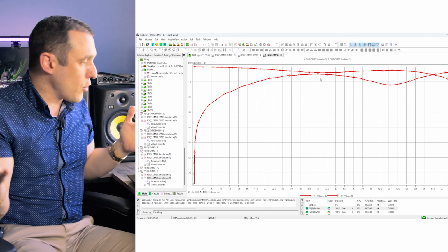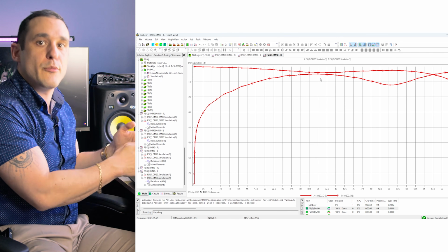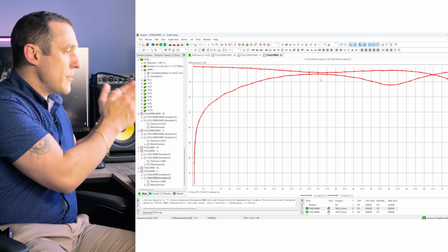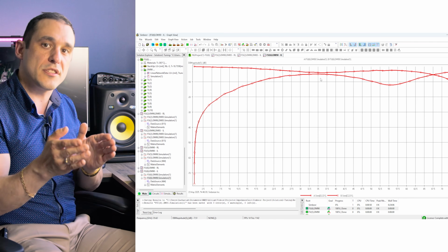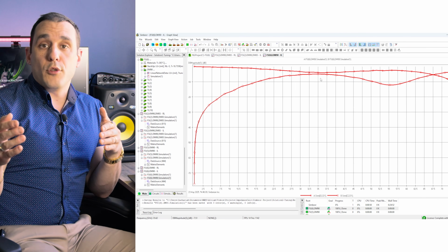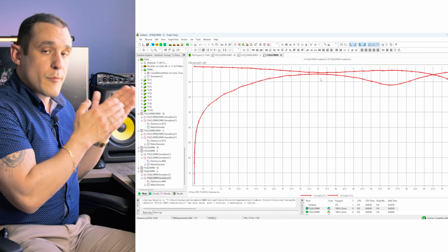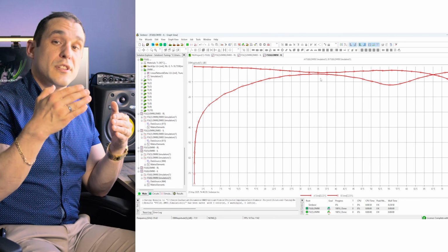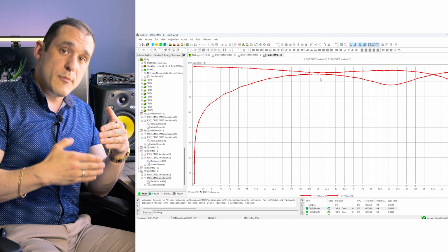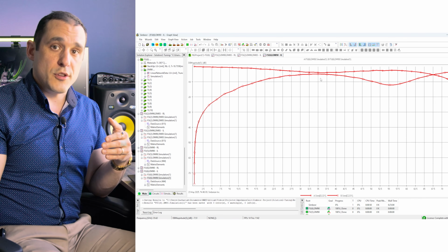The other reason this is important is because if we were to place this signal onto a cable and we had a lot of mode conversion from that differential signal into common mode signal, that could create a radiated emissions failure. The limits on common mode currents on cables are actually very low, and if you had a lot of mode conversion from a differential signal into common mode, and that common mode signal got out onto a cable, that's what could then create a radiated emissions failure.